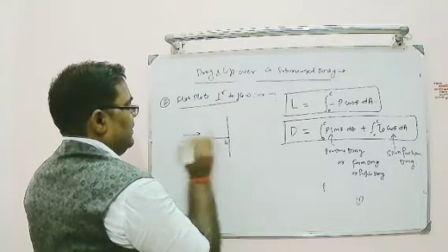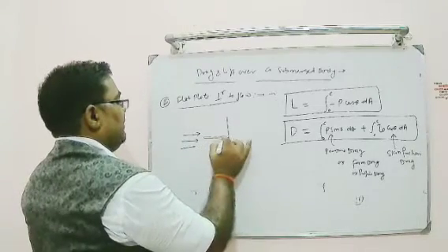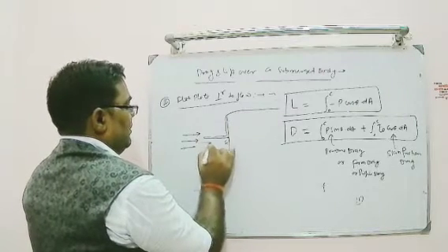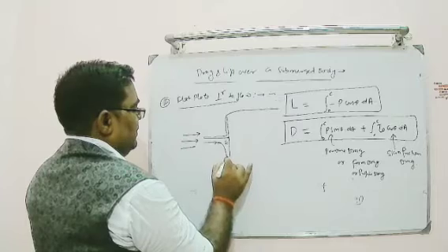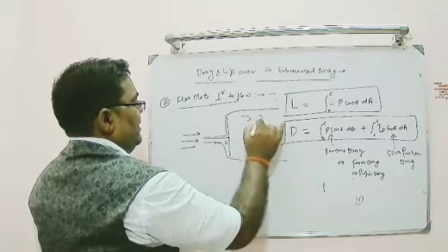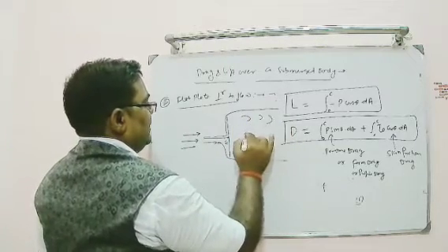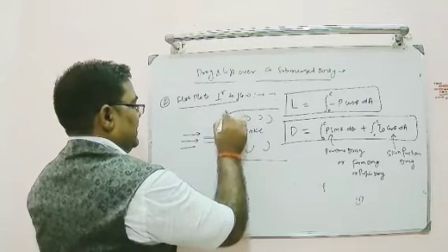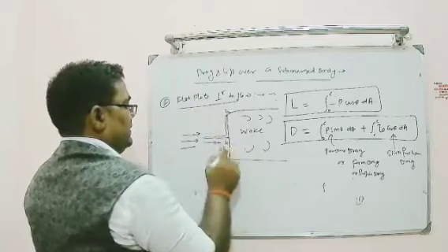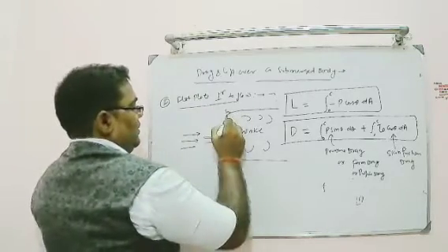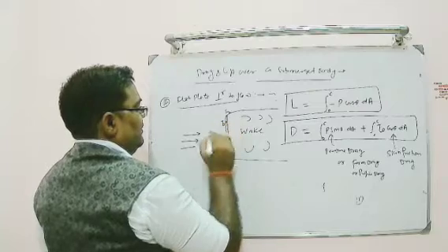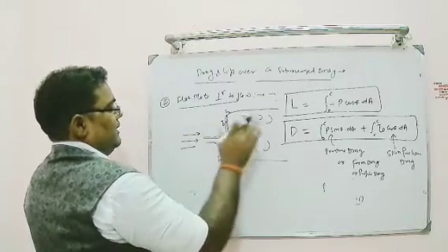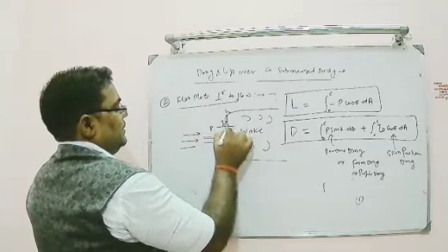First, we get a stagnation point here, and after that the flow travels like this, and at this edge it starts separating. Similarly, flow comes like this, reaches here, and separates from here. The moment it separates, it creates this kind of vortices. This is called the wake. Along this there is another stagnation point, so we can say this is S1 and this is S2. Along this direction, shear stresses will be acting, and pressure will be acting like this, and pressure from this side.